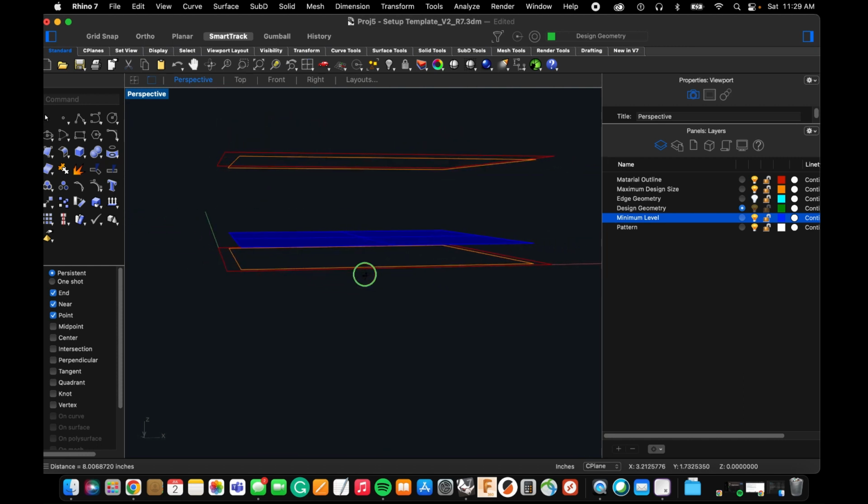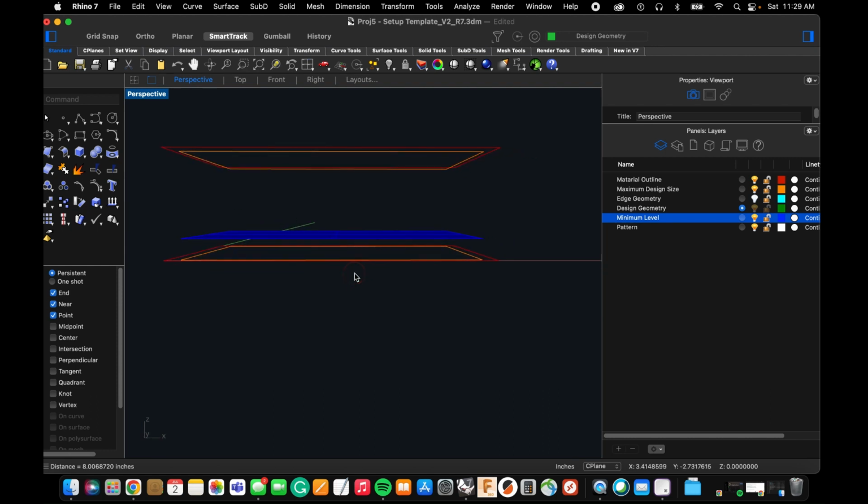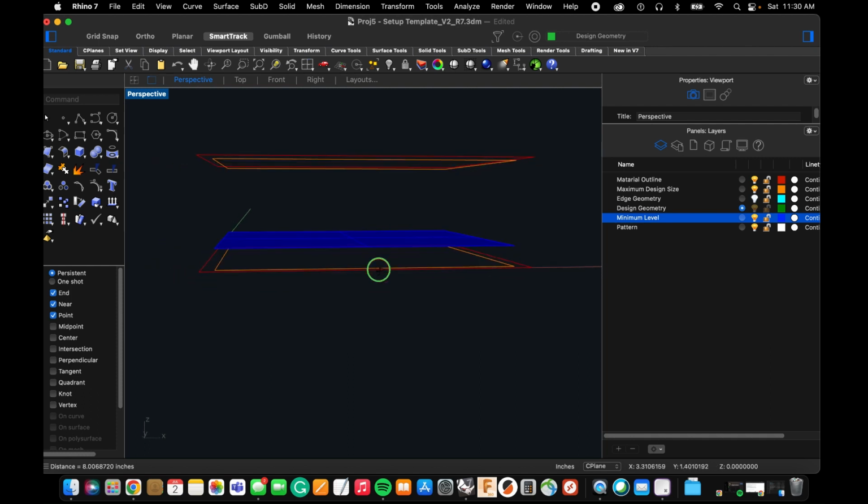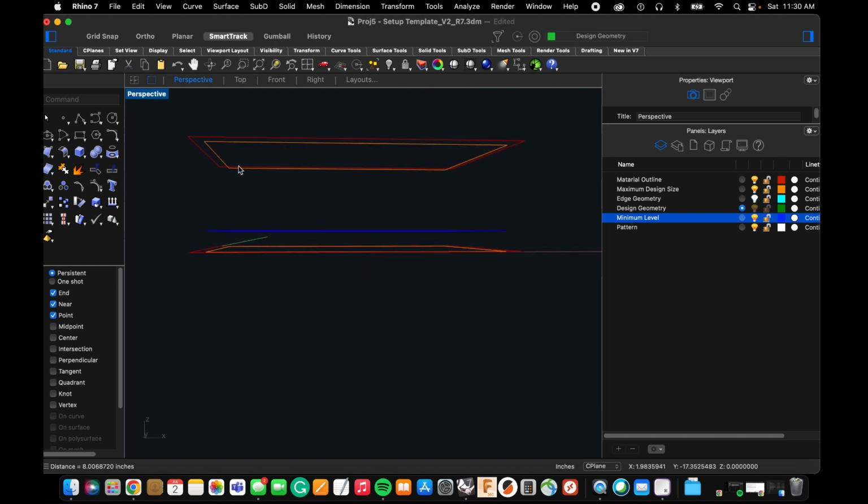And that depth is actually tool dependent. So the 1/2 inch tool would go the deepest, and it's going to go half of the radius, 1/8 of an inch. A 1/4 inch is going to go 1/16. The 1/8 inch is going to go a 32nd, cutting into the surface that we're making.